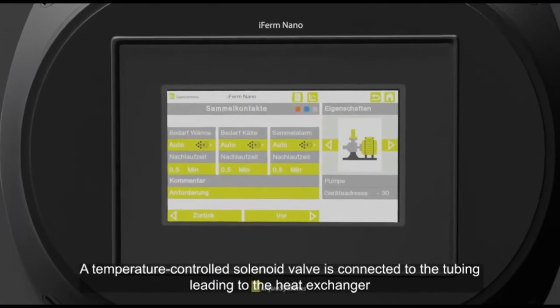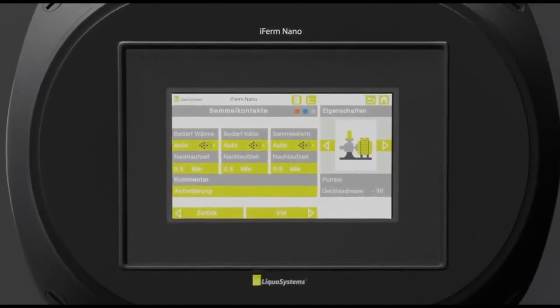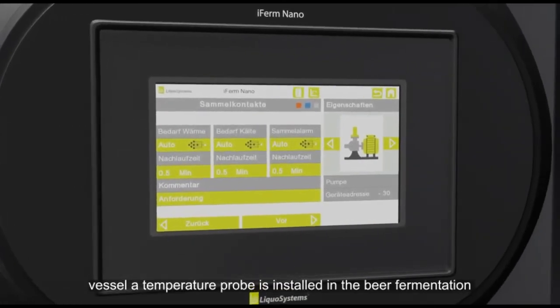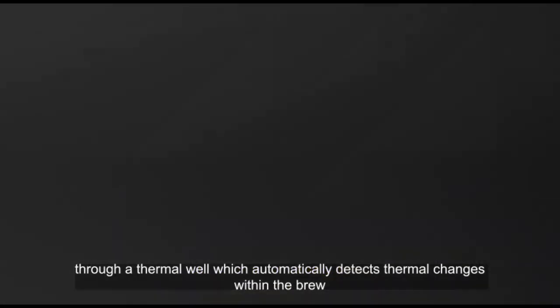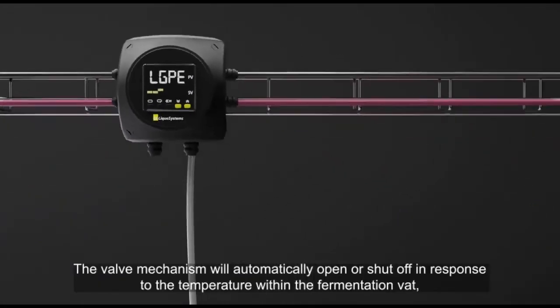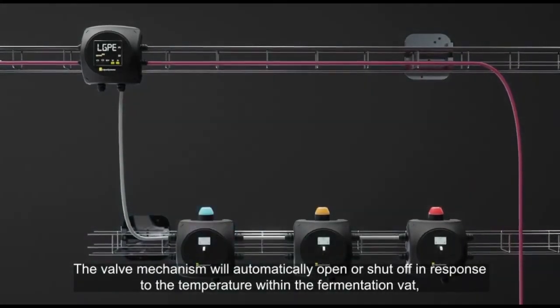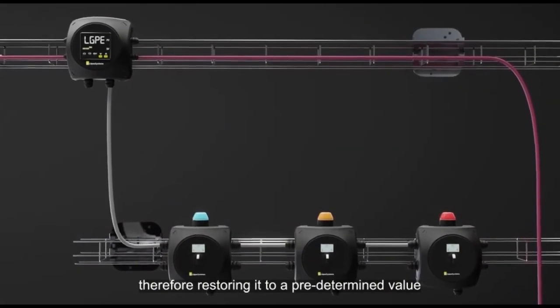A temperature-controlled solenoid valve is connected to the tubing leading to the heat exchanger. Additionally, a temperature probe is installed in the beer fermentation vessel through a thermal well, which automatically detects thermal changes within the brew. The valve mechanism will automatically open or shut off in response to the temperature within the fermentation vat, therefore restoring it to a predetermined value.